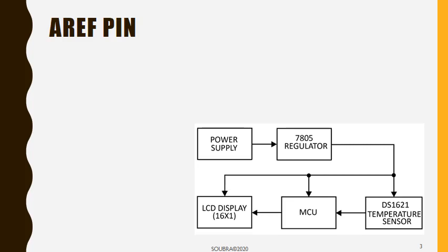So here's my temperature sensor connected to the MCU, and I should have, outside or inside the MCU, some kind of converter. It's a trick question, but I mean, come on, I'll take any answer. So my ADC that allows me to go from analog to digital, should it be inside the microcontroller or outside? I don't really care as long as it's there. The sensor itself could have it inside, right? It could be somewhere in between the connection, or it could be inside the MCU. And we're going to find out that most probably you're going to find something inside the MCU. It's easier for everyone. And there's an ADC in an MCU, usually.